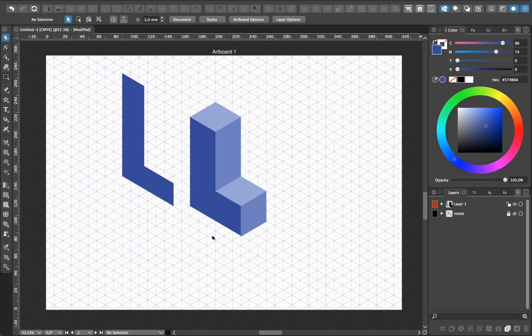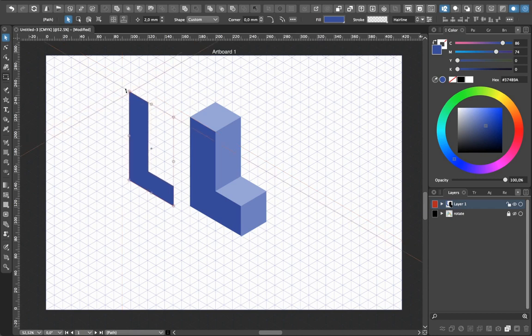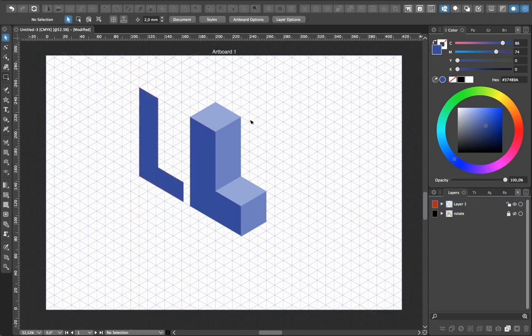It can be a waste of time if you're very familiar with the pen tool and if you know how to use the pen tool for square angle shapes like boxes, T-shapes, etc. It's not necessary, but it can be interesting if you talk about complex shapes like a star or some text. If you want to put some text, let's say you want to make a house or a shop and you want to put some text in isometry, you have to use this method.